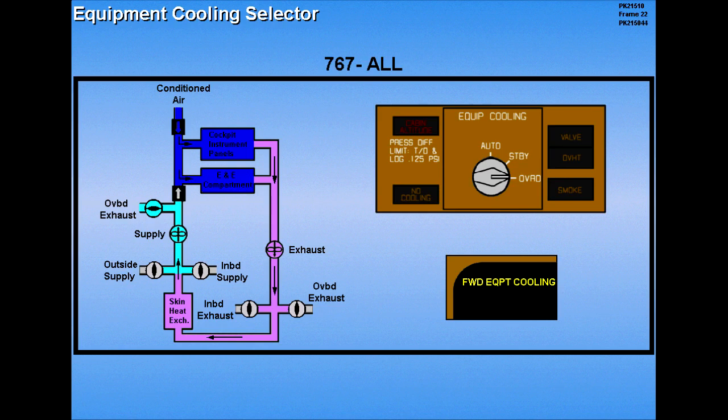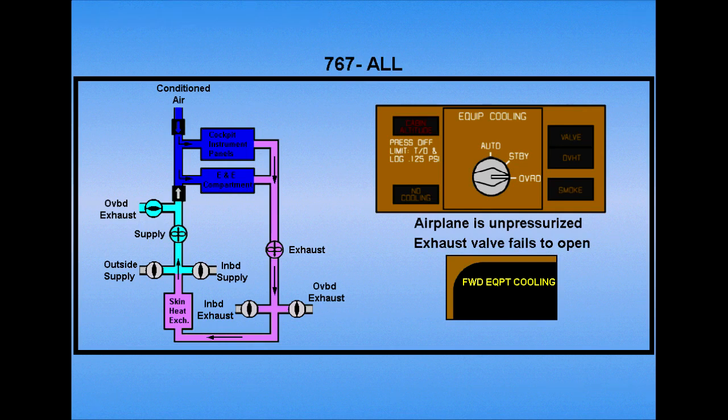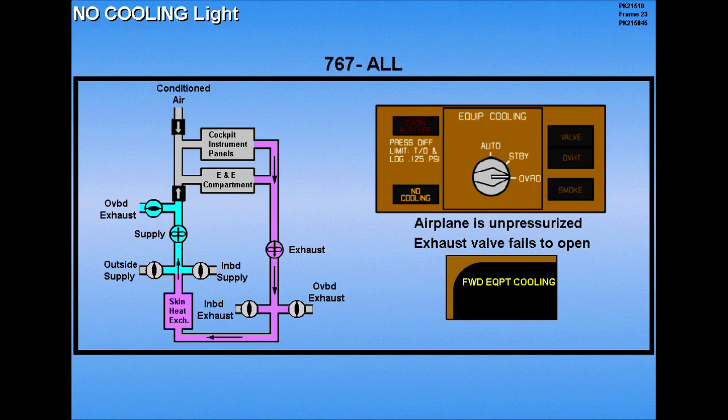Keep in mind, however, that the equipment cooling air will not exhaust if the airplane is unpressurized or if the exhaust valve fails to open. The no cooling light illuminates if the selector is in the override position and no cooling airflow is detected.